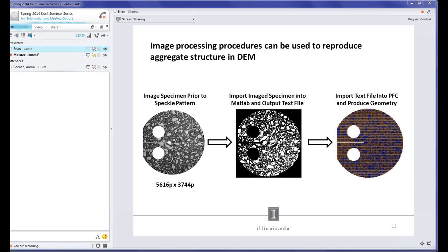I don't like using really large aggregate mixes in fracture tests because I don't think that it's a good idea. But I try to stick to 9.5 millimeter nominal max aggregate size mixtures. So I think, what is that, like the 12.5 is the top size for these samples. But I have seen that, at times we'll test mixes that have 25 millimeters, so an inch, and yeah, that really creates some issues with some of the COVs that you would get.